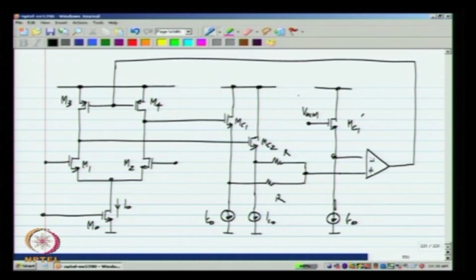We will see how to make this particular op amp shortly. Okay. So, right now this is what the circuit is. And you can also see that in the differential picture, this point will be at ground and these two will in the ideal case offer no loading. In reality, because of CGS of MC1 and MC2, there is some small loading on the single stage op amp.